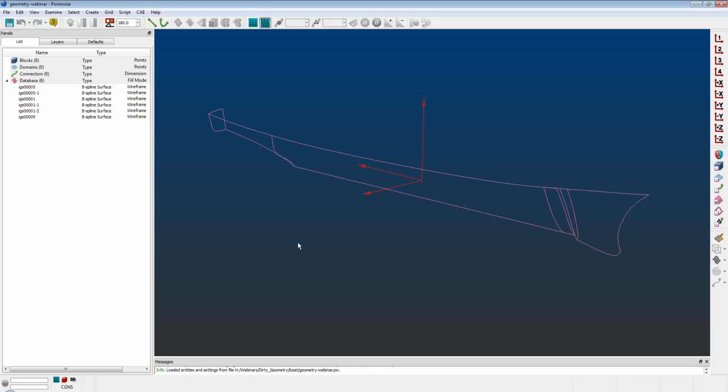So today we'll be showing Pointwise's facilities for cleaning up and dealing with this geometry. You'll see some of the many tools it has for importing, creating, and modifying geometry. And it has a couple general methods for meshing on the geometry. The first is something we call fault-tolerant meshing. Fault-tolerant allows you to heal the mesh over faulty geometry, and then you fix errors on the mesh level. The other, called solid modeling, allows you to heal the geometry first and then mesh on the healed geometry second. These two techniques are not mutually exclusive, and they can be used together, and we'll be demonstrating both of these methods today. So while the focus of the webinar today will be geometry cleanup, we'll also include some meshing techniques to help with the explanations.